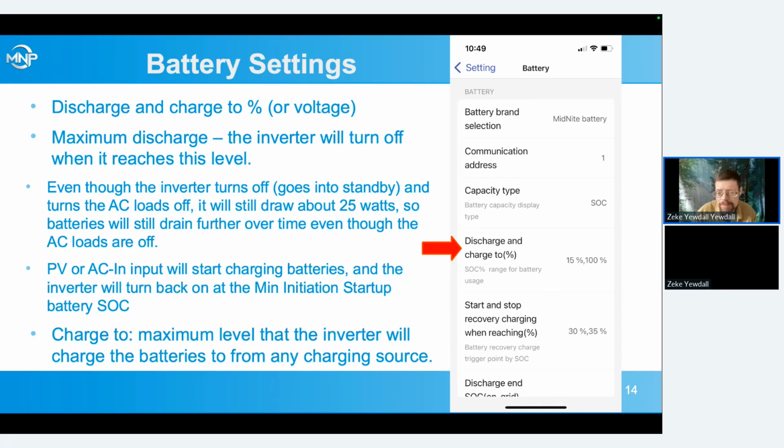So you might just top it off a little bit at a low rate rather than at full power all the way to 100%. And that's just in case something goes wrong with the programming and the battery is discharging even though the grid's present, we're going to use the grid to keep the battery from bottoming out.